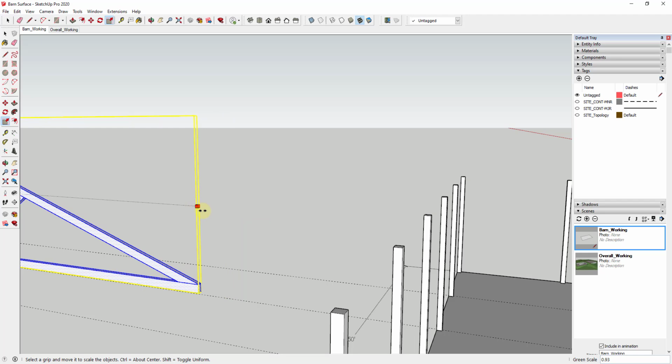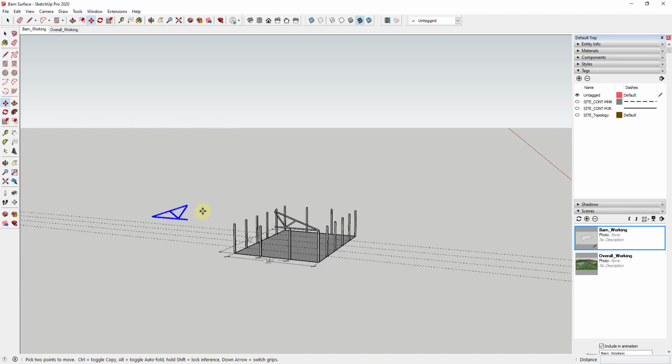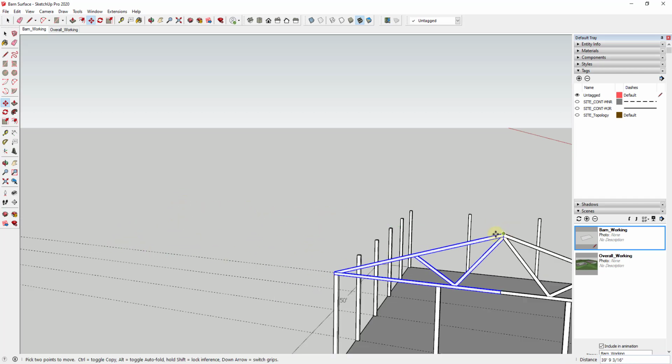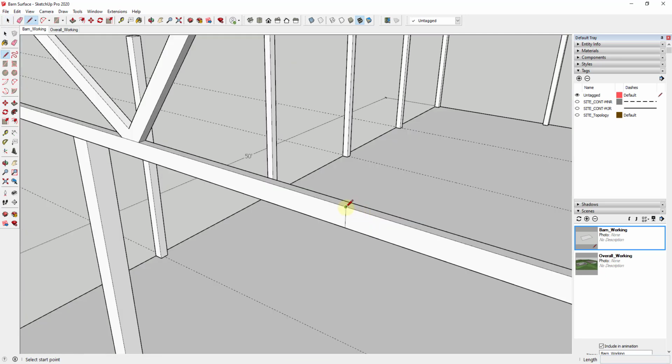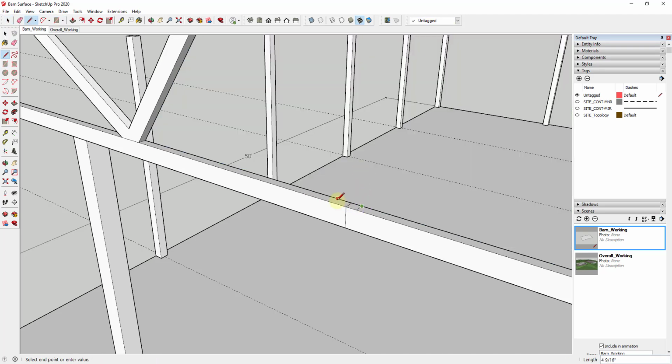Make sure that you get this central point when you do this, but I'm just going to type in -1 and move this across. And then we can bring this back so that our pieces come together right here. And so now I'm just going to add my central 2x4. So I'm just going to type in 0.875 on one side here, draw a line across, and then 1.75 over here. And basically what we're doing is we're roughing out the size of a 2x4.